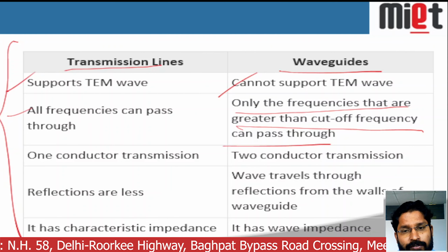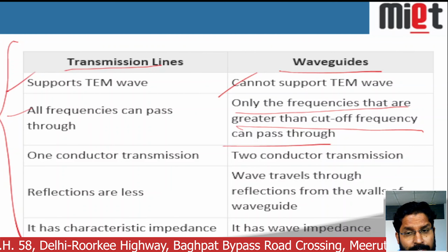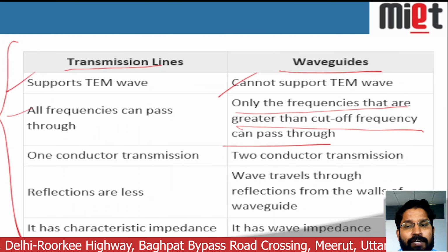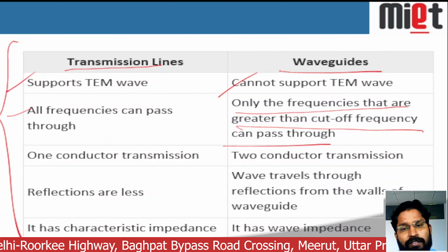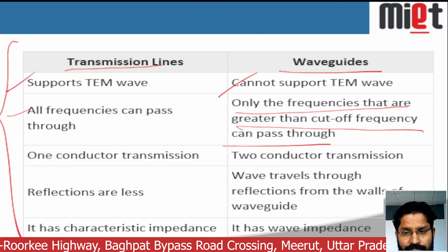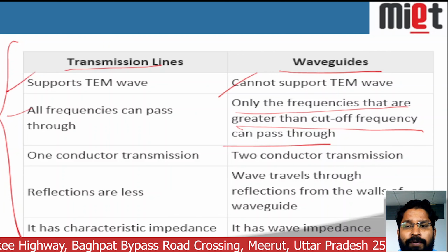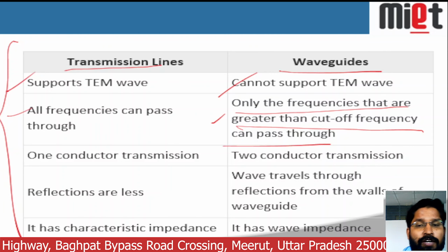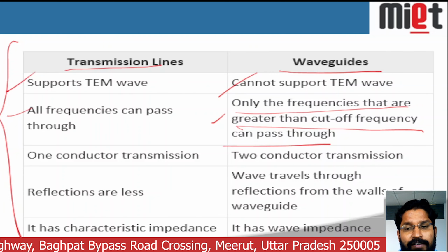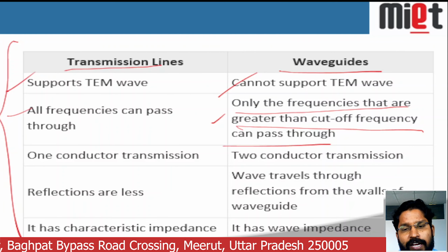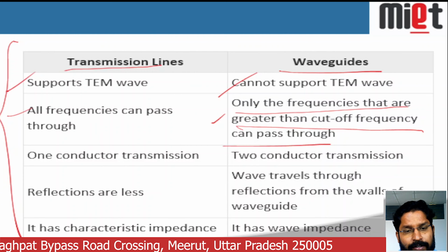It is very important to note that the waveguide works as a high pass filter. It means below the cutoff frequency, the wave does not travel inside the waveguide. Only frequencies greater than the cutoff frequency can pass through the waveguide.